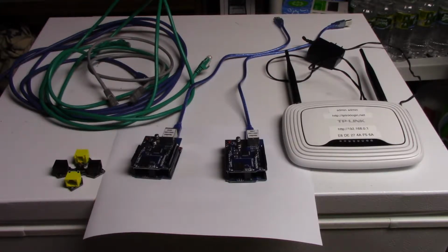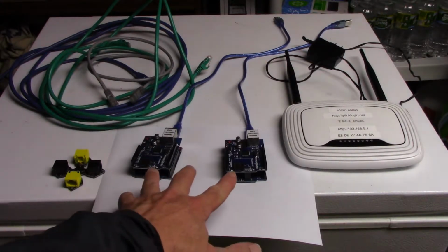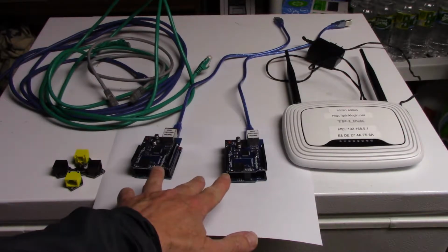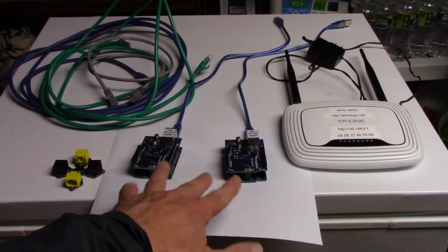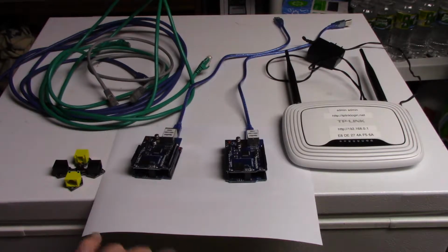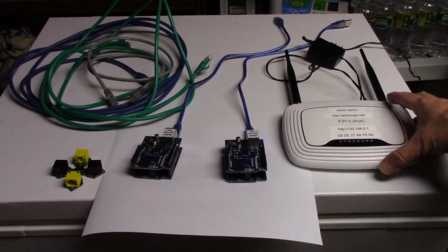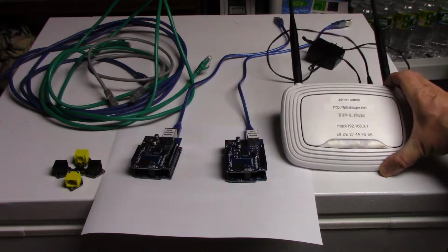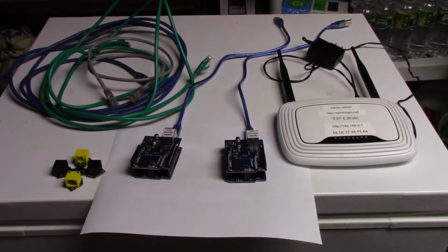Now in your setup, the main thing is just having the two Arduino Unos with the Ethernet shield so they can communicate with each other. You may not need all this stuff. I also had used hubs, and hubs will work, and also any of the big Ethernet switches will work, but I had tried some of the smaller Ethernet switches and those won't work with this. So what works good is just the wireless router, but not using the wireless part of it, just using it as a switch seemed to work good with this.